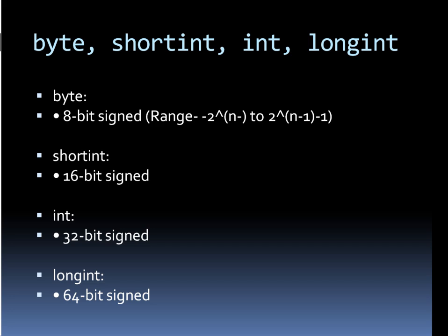Suppose you have logic 7 to 0; you may be tempted to replace it by byte. Now, hardware designers should be careful as these new types are signed variables. So a byte variable can only count up to 127, not 255. You have to remember it again and again, okay? You could use byte unsigned, but that is more verbose than just bit. If you use byte unsigned, then you can use values from 0 to 255. Okay.